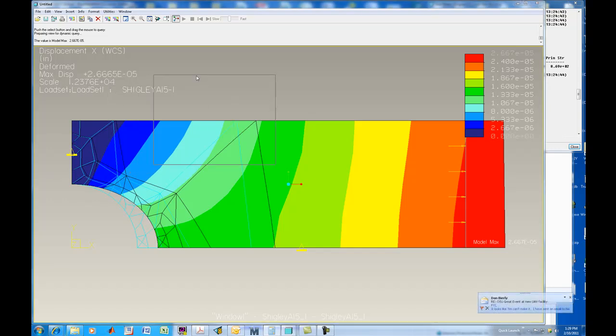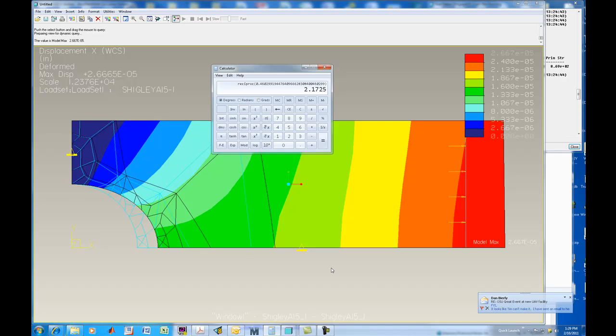If we were going to calculate this deflection and assume that the entire thing was a complete rectangle, we would use an FL cubed over 3EI. The F would be 100 pounds, L would be 3 inches, E is 29 million. If you look up the material properties, and maybe we should do that in a moment, the E is 29 million. The I would be, no, that's FL over AE. Sorry, I was thinking the wrong thing. FL over AE, so that's going to be quite easy.